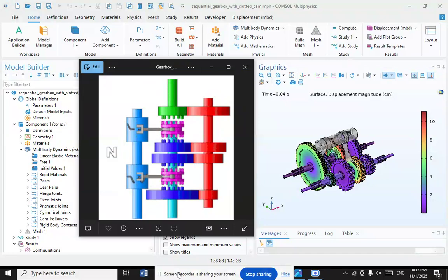On a sequential manual transmission, the shift lever operates a ratchet mechanism that converts the fore and aft motion of the shift lever into rotation of a gear shift drum or selector drum, sometimes called a barrel, which has three or four tracks machined around its circumference. Selector forks are guided by the tracks either directly or via selector rods. The tracks deviate around the circumference, and as the drum rotates, the selector forks are moved to select the required gear.